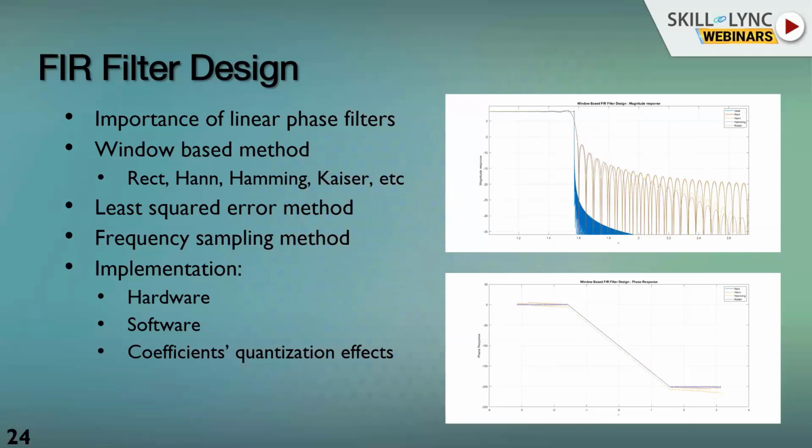So what we do is truncate the filter using some windows and still get the desired stop band attenuation of the signal. You can see the attenuation of the ideal filter is around 35 dB or 40 dB, but this is not practically implementable or realizable, as I have explained. So we take different windows around the ideal filter, and when we take the window, we have two problems.